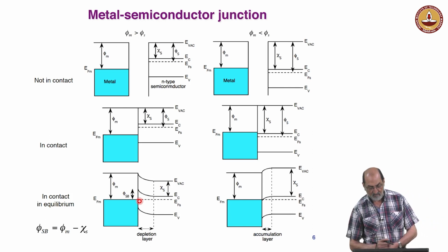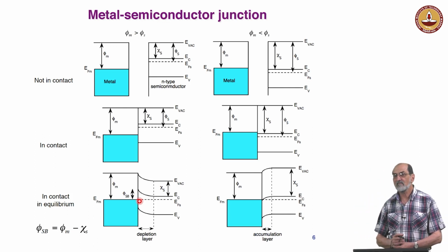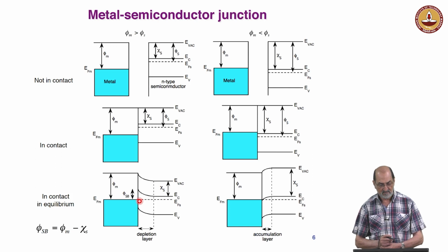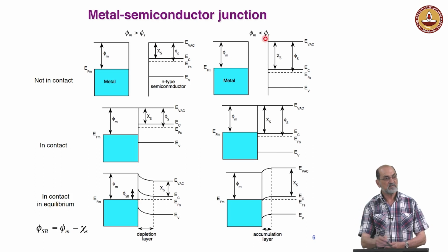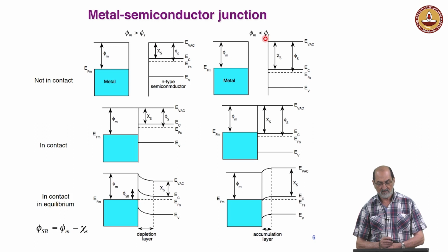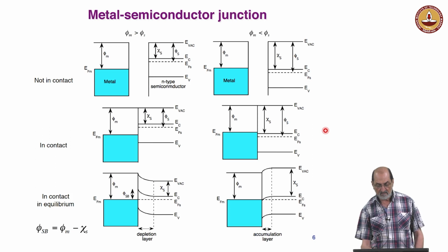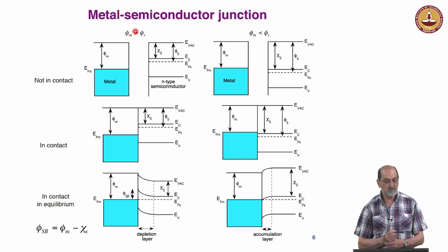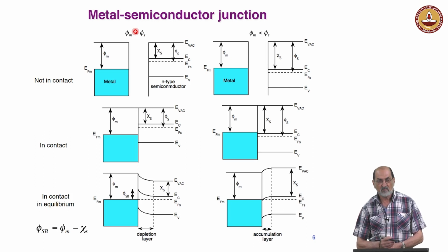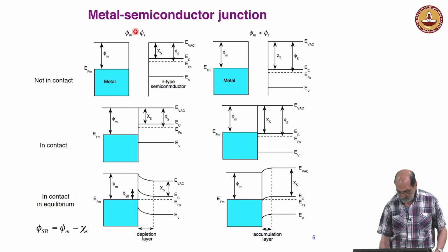Good. Fortunately, apparently, people say that for oxides, this is quite true. This works quite well. That's for small work functions of the metal, or high work functions, the barrier forms or not, following this scheme, but not for covalent semiconductors.